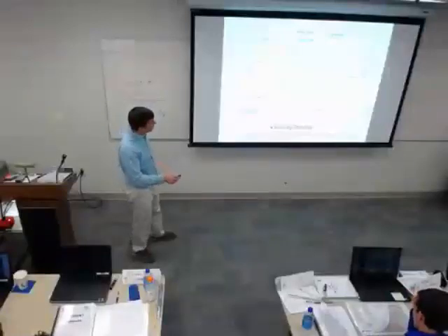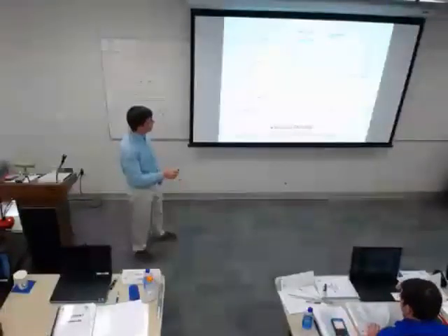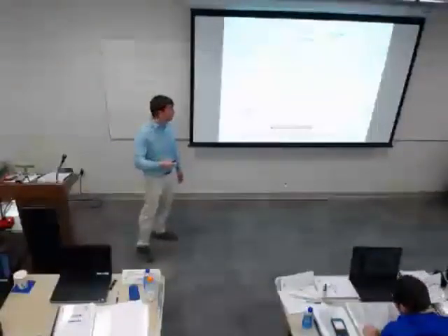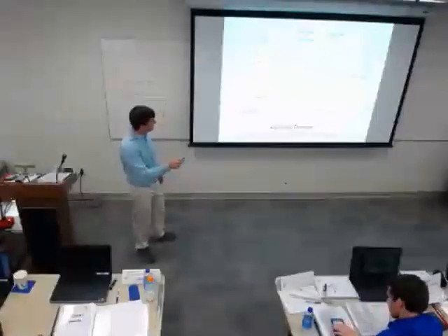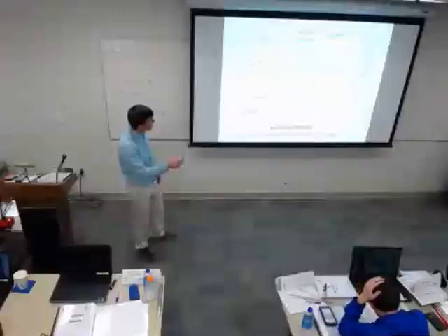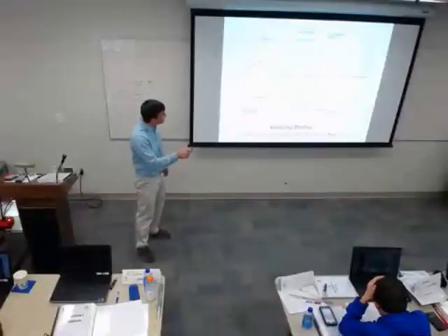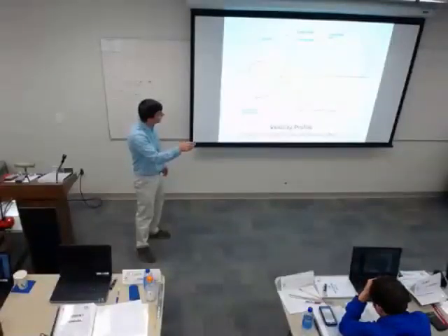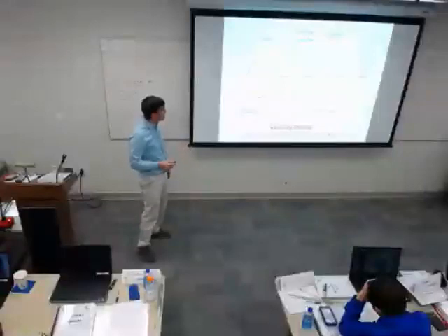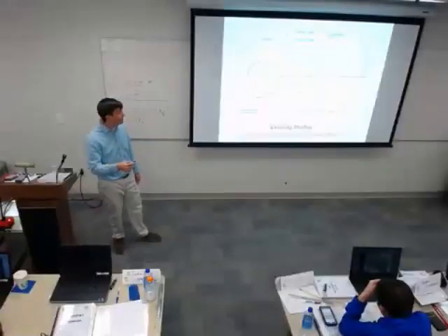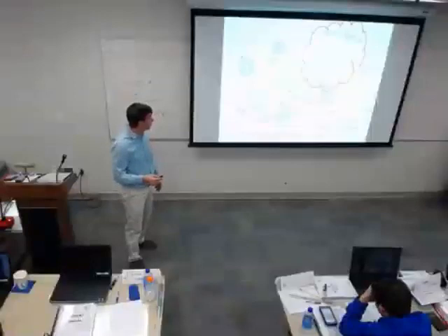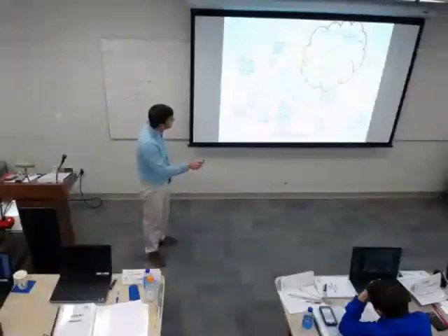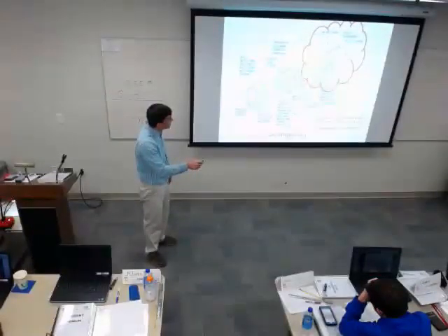If my duct is shorter coming off of this fan, then it needs to develop this full profile. It's actually not going to perform as well. That's dictated by if the fan has this little cutoff in it. Obviously, there is less surface area on my duct. I'm going to have a duct connection here, but you can see that the actual area leaving the fan is a little bit less. You have to find that on your fan submittal if that exists. This is just showing that in 3D. So here's your total size of your fan outlet, and there's a cutoff inside of it.